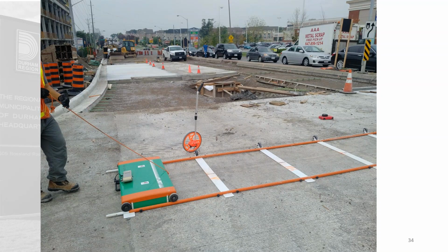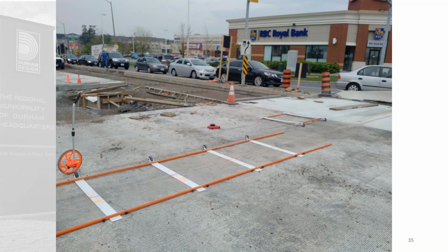We also specified MIT Scan 2, which was used to verify the position and alignment of the dowel bars. We had them do it on every 10th joint, to make sure that the dowel bars were where they were supposed to be, and that the alignment of the dowel bar and the depth was proper. So that dowel bar should be about mid-depth of the slab. So we specified this, and it was fine. It probably didn't really need to have them do this. This is more for if you're doing highway construction, and we could pretty much inspect all the dowel baskets and watch it get paved and know that it was in the right place.